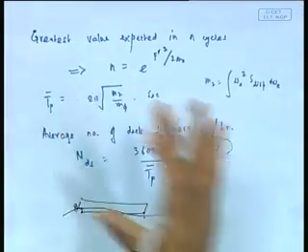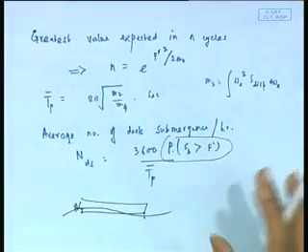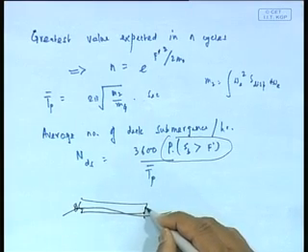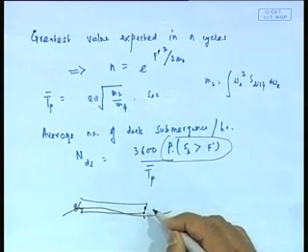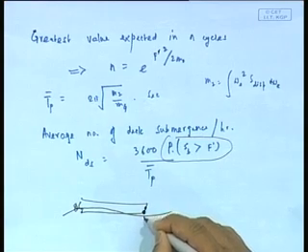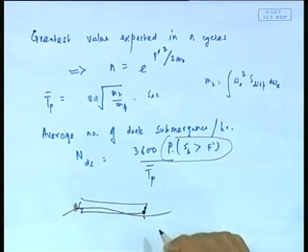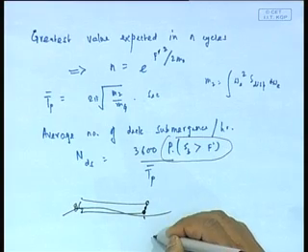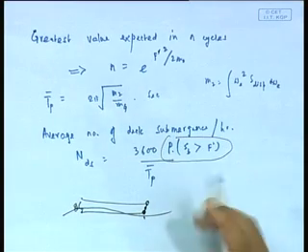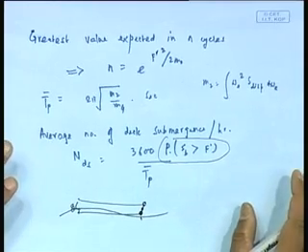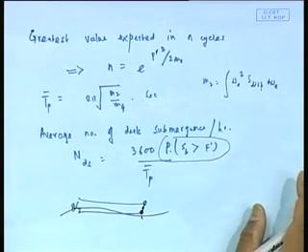Different condition, SB must be more than this, or must be less, whatever. All of them are measuring some particular point. In this case, I will be measuring this bottom point, whether it is coming out of water. In deck emergence, I am trying to find out the top point, whether it is going below water.